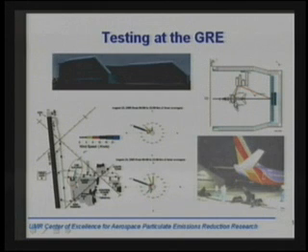We had measurements at the exit plane on both engines. And then on the engine on the right-hand side, as you were looking from the aft, okay, then we had measurements at 30 and 50 meters behind so that we could get information on how the plume was evolving in the near-field plume. This picture down here actually shows you the two probe stands holding the probe rakes, okay, that were pre-mounted in position here to align with the engines on the aircraft. Fortunately, there's a slight adjustment on each one that you can do so you could align to the engines as they're found on both the 737-300 and 700.